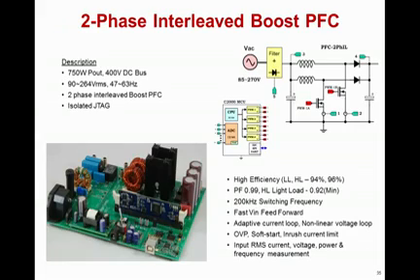We have several reference designs that are specifically targeted at applications that commonly use or could benefit from digital control. The first of these is a 2-phase Interleaved Boost power factor correction board. The diagram in the top right shows you a PFC power stage. The green tags represent points at which you want to make measurements with the ADC, and the red tags indicate points at which you would control a FET with a PWM output. These are then tied to a C2000 microcontroller that has on-chip ADC, PWM, and CPU.